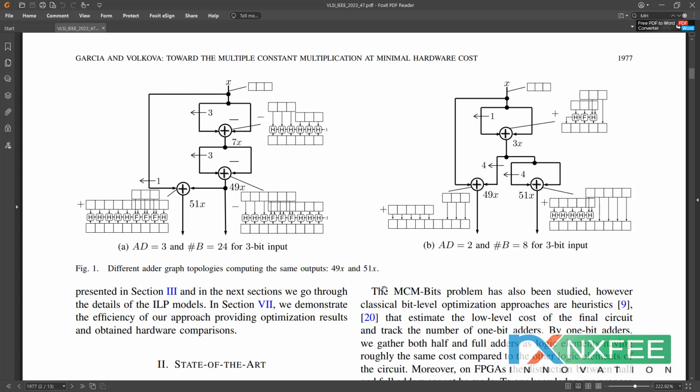We also need to reduce the number of partial products with a number of stages. Next, the 8 by 8 multiplier provides a 16-bit output, so after the multiplication process we also need to use a 16-bit adder. But here we can truncate.